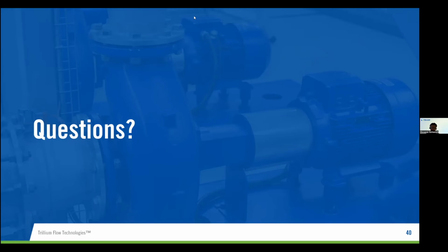The availability of a great population of data coming from the pump allows us to develop predictive maintenance programs, basically by comparing the hydraulic performance of the pump over time with design parameters, providing data relevant to a possible derating and its evolution over time. And this is from a hydraulic point of view.